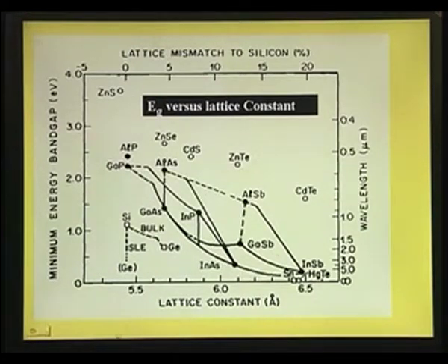Now, you can have here indium phosphide, which has a slightly higher band gap compared to that here, and that is also direct band gap. I can mix gallium indium arsenide of this composition with indium phosphide, or I can grow gallium indium arsenide on indium phosphide. See that the vertical lines indicate that there is a lattice match between the two compounds. This one slide contains so much packed information. You can see here, this material at this point has a lattice constant of 5.85 or something like that. If you take indium phosphide, the line goes vertically up, it has the same lattice constant.